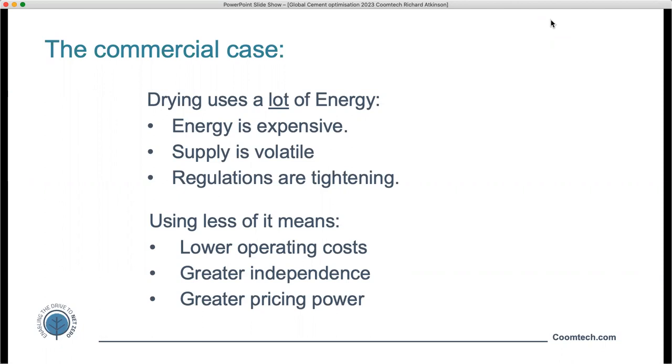Firstly, you have to be able to pneumatically convey the material. This means a particle size limit of approximately 5 millimeters and a reasonably free-flowing character. It's ideal for sand, fly ash, GBFS. It's no use for gravel, too big, and anything that's very sticky just isn't going to disperse enough in the air to be dried. Secondly, the water you want to remove has to be on the surface, because we have to be able to get at it with the air knives. If the water is down inside fissures in the material, this system will not easily remove it.